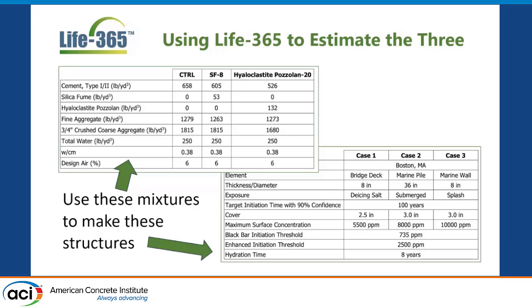And then for a marine wall, in the past we've modeled that as a slab that's tilted up. That makes sense as long as you just got splash on one side and not on the other. If you got splash on both sides, you really have to go to something that's more like a marine pile because you're getting hit from a number of sides. And you want to be able to make an expert judgment, if you will, about the most realistic level of chloride exposure and intrusion based on your structural type.